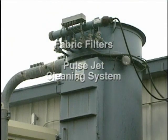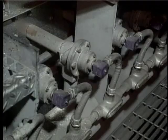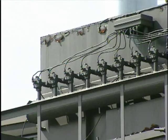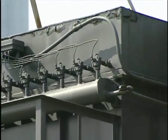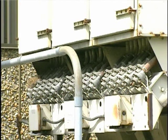The cleaning system consists of a compressor, an aftercooler, a dryer, an oil trap, a storage manifold, solenoid and diaphragm valves, and laterals or blow tubes. The compressor generates relatively oil-free compressed air that is delivered to the storage manifold at about 60 to 90 psig. The aftercooler cools the compressed air as it comes from the compressor. The dryer removes moisture, and the oil trap removes any oil that might be present.